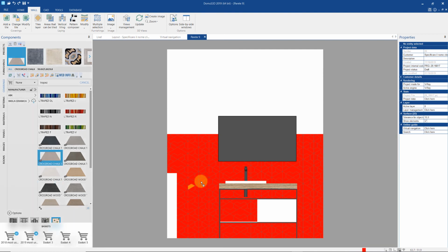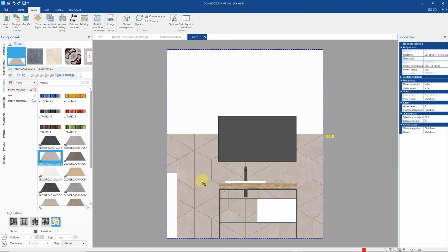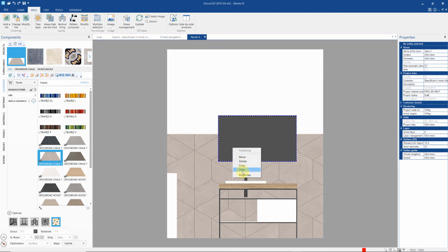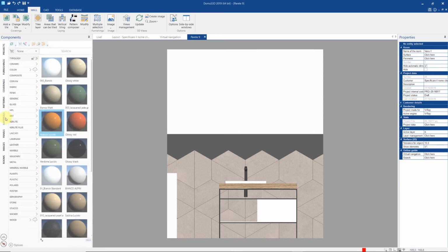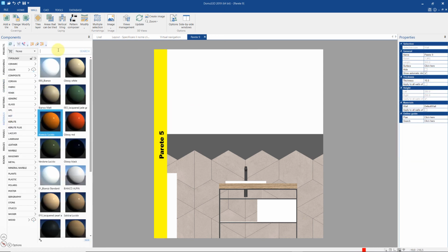Now we have a strip with the preset height with our trapezoid pattern. If we want, we can add more strips above it. Or with the command Modify Delete, we can select and delete certain tiles so we can highlight the upper part of our strip. Below the deleted tiles, the material used for the grout will remain, but it's possible to apply a different plaster quickly.